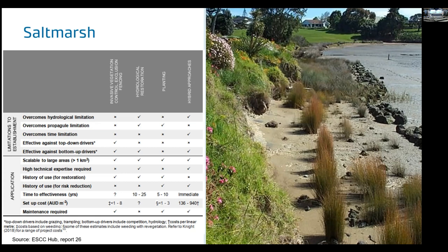In Auckland, we're currently looking at the Onepoto Basin, doing a similar salt marsh edge restoration, but with a protected sill. And the reason why you do a sill is to take a little bit of the sting out of the wave heights to allow the salt marsh to generate and grow. It's also that hybrid approach gives our clients some confidence that we can deal with the effects of rising sea levels by having a way of managing that edge.